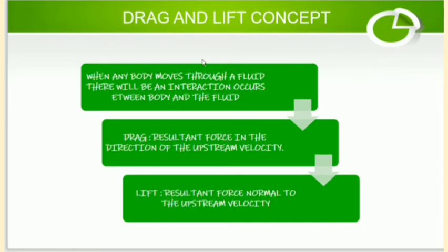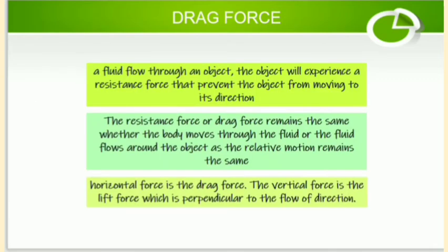Drag and lift concept. In this concept, we explain that when any body moves through a fluid, an interaction occurs between the body and the fluid. What is meant by drag? Drag means the resultant force in the direction of the upstream velocity, while lift is the resultant force normal to the upstream velocity.